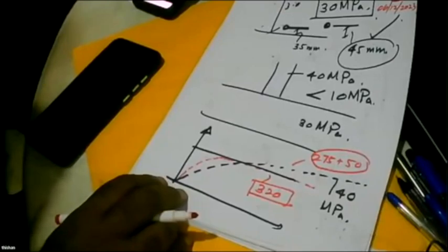By the time the maximum dead load comes on, the raft is not a 30 megapascal raft, though you designed it as 30 megapascal in 28 days. Now 2 years have gone, you have cured it properly, you had fly ash to continue the reaction, and if you take a core, you will see the real concrete can be ranked as 45 megapascal cube strength concrete.